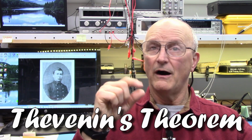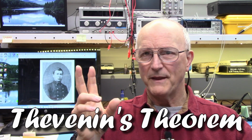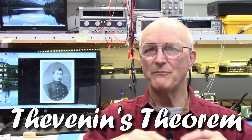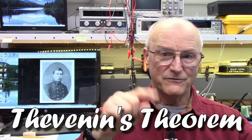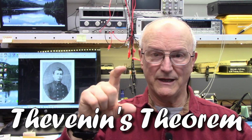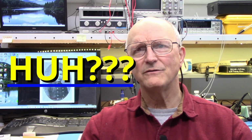We get R sub TH by shorting all voltage sources and opening all current sources and then calculating the remaining resistance value. We get the voltage V_TH by calculating the voltage at terminals A and B with them open circuited. Now, are you confused?